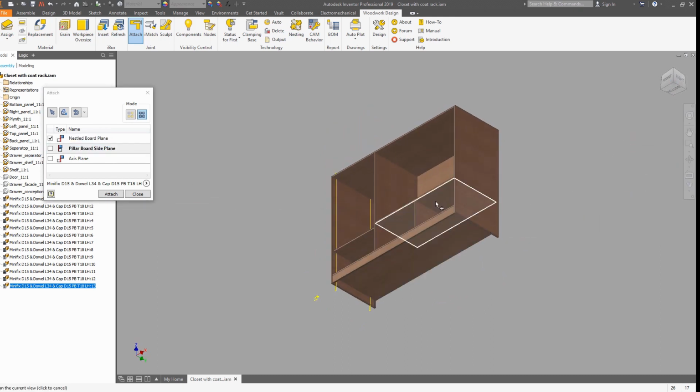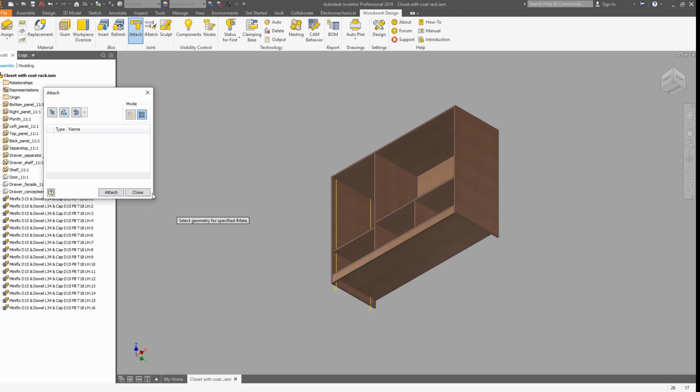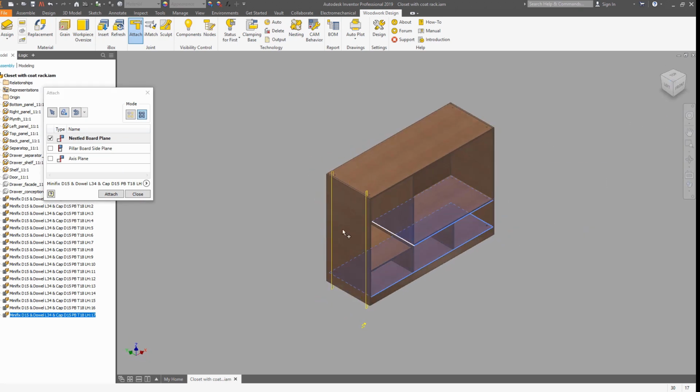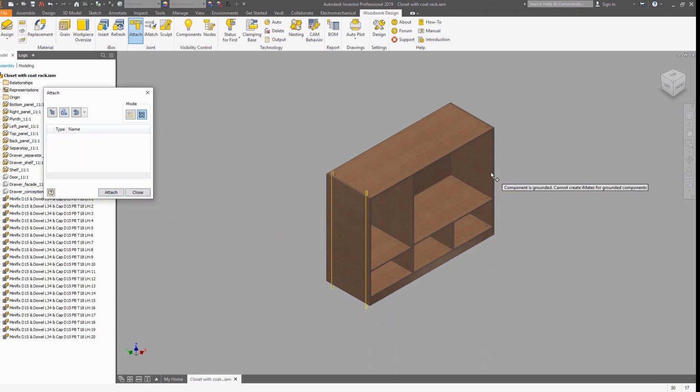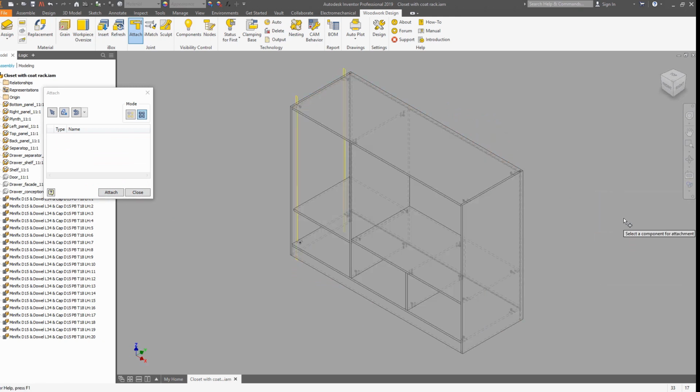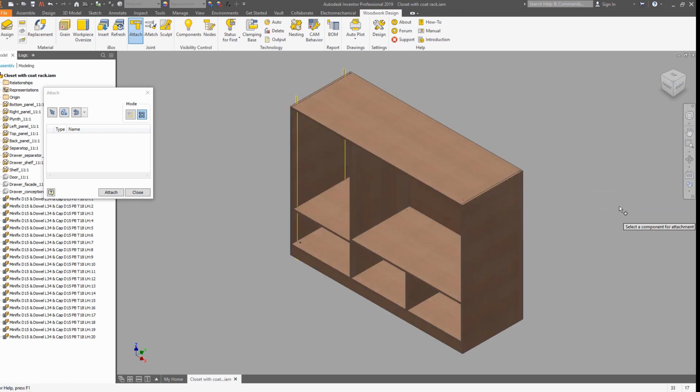Try not to apply them in one step, because it's easier to split this operation into multiple steps and just choose the appropriate geometry. Otherwise you may get an extensive amount of hardware items in all the intersections of the selected geometry components, which is not good. So the tactic here will be to divide your workflow into multiple stages and just pick the geometry items for each of those stages, and that's it. So now you can see that there are some hardware items already in place.